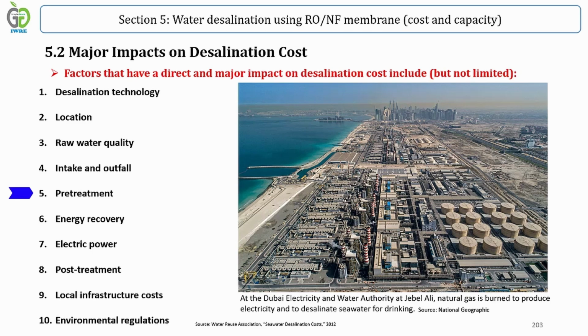Some raw seawater or brackish surface water sources have a high level of organics and biological activity and require more robust pretreatment technologies such as dissolved air flotation and ultrafiltration. Other raw water sources that use submerged intakes or well-based intakes may require less pretreatment, such as a single-step media filtration or microfiltration.